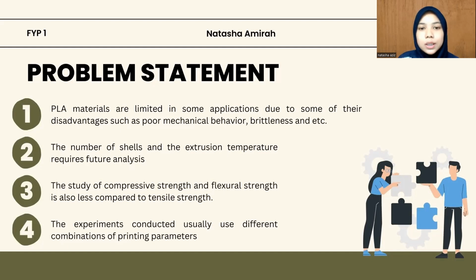The first one is PLA materials are limited in some applications due to their disadvantages such as poor mechanical behavior, brittleness, low crystallinity, and low crystallization speed. Therefore, PLA has been modified physically and chemically to expand its use by improving its properties and quality.